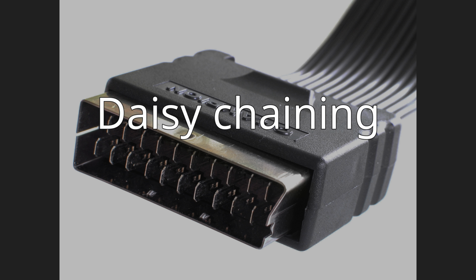As long as all devices have at least one up and down socket, this allows for connecting a virtually unlimited number of devices to a single Scart socket on the TV. While audio and video signals can travel both up to the TV and down to devices farther away from the TV, this is not true for RGB and non-standard YPbPr signals, which can only travel towards the TV.